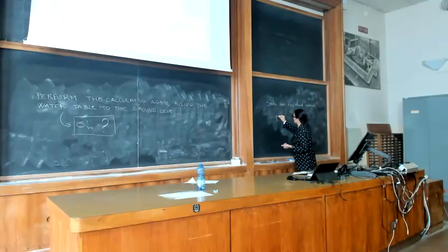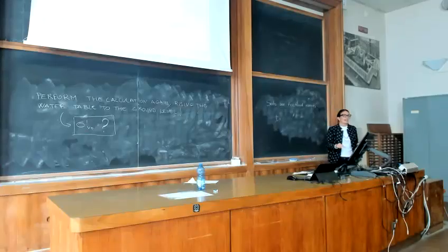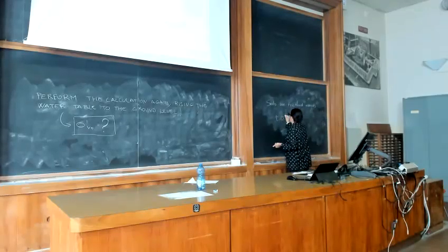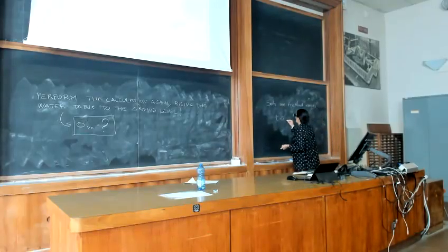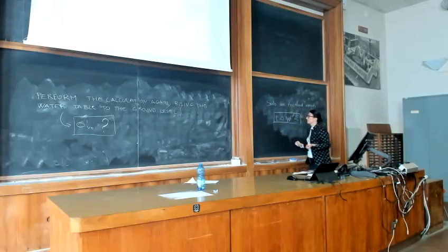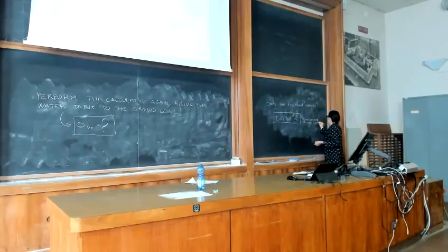Okay, so in general we can write that tau, the shear strength of a soil element, could be defined as a function of sigma dash tangent phi dash plus c dash. This is the Mohr-Coulomb failure criteria.